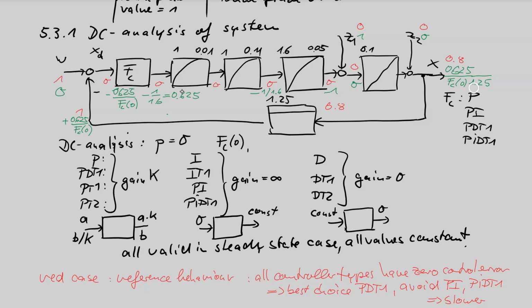What do we want to have here? We want to have, of course, a 0. I can only get a 0 here if the controller gain is very large, going to infinity. Control error is 0 only if the controller has a very large, possibly infinitely large gain. So we can conclude, if there is a disturbance in front of my integrator here, then this integrator is not a help.